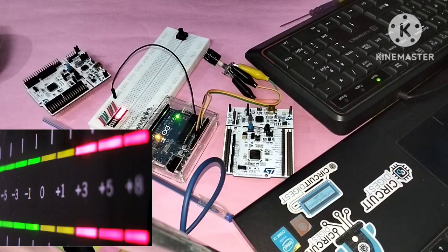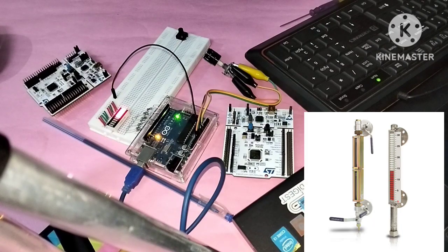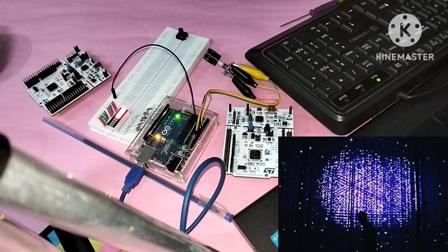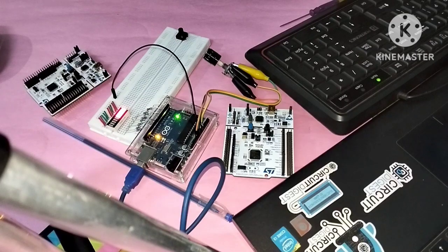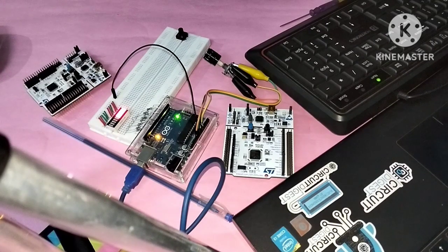You can also set it for analog sensor monitoring, like a temperature sensor. You can set the ranges by using RGB LEDs there, so that if the temperature is increasing, two LEDs will be red, and the low or minimum temperature will be in green. You can set those things, or use it with light sensors. And you can use it in interactive art installations, like visualizations for museums, or as you have seen in restaurants. You can use multiple LEDs, even 100 of them. I have already told you how many components you need.